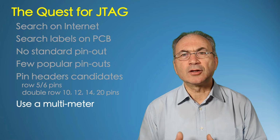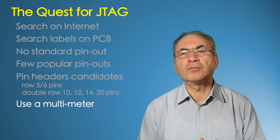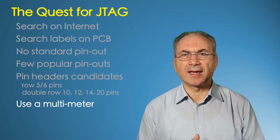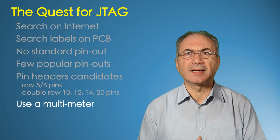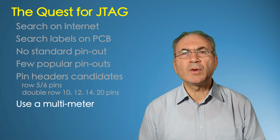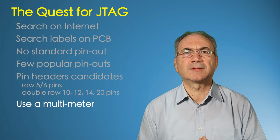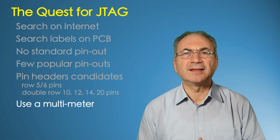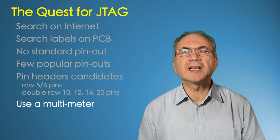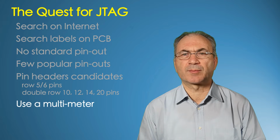Test reset usually has a pull-up or can also have a pull-down resistor, and TDO should be a high impedance input. Once we have identified with the multimeter ground and VCC and taken pin resistance and voltage measurements, we can compare what we have found with the popular pinouts on the JTAG test website, and if we are lucky, we can identify the JTAG pinout using only a simple multimeter. We will see later a demo of this approach.